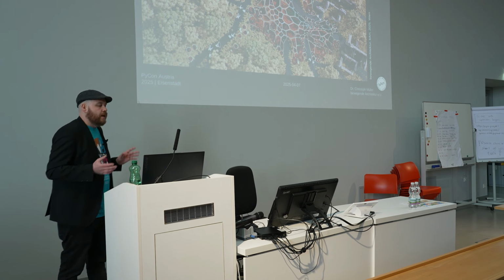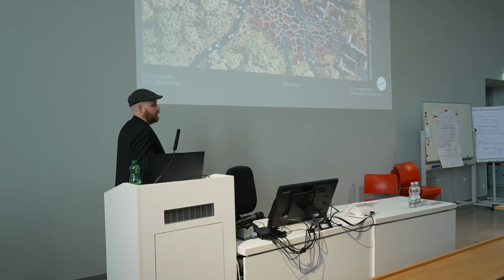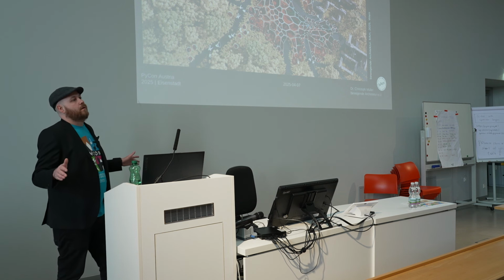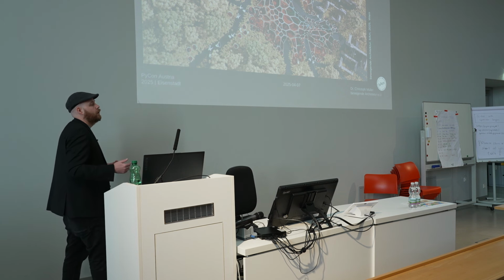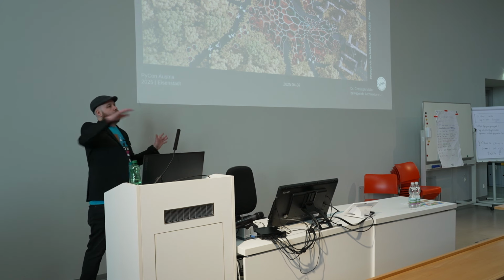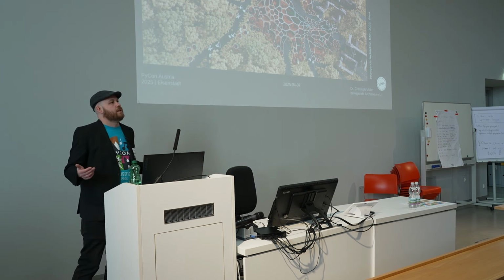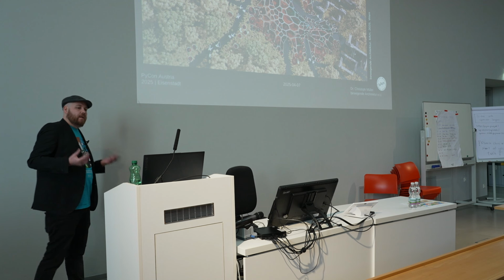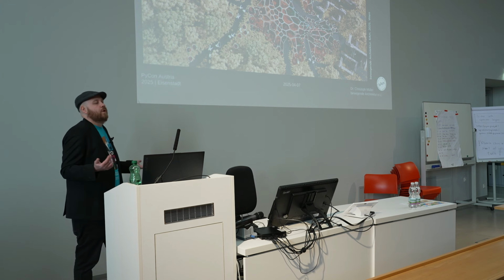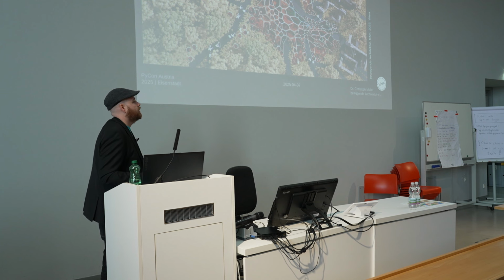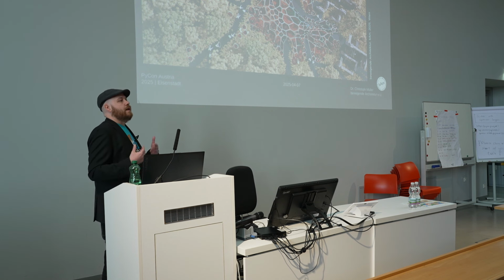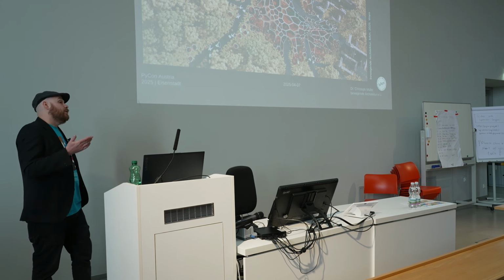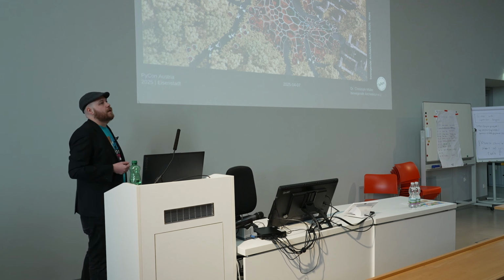But in a membrane structure, there is one very beautiful thing. They are getting more efficient the bigger they are. If you take a look at these Frei Otto structures, there are very large scale structures that are getting more and more efficient the bigger they are. And the statical performance you can compare to a Traglufthalle. I don't know how to call this in English, but it's like a tennis court, where you only have a membrane and you pump it up with air. But to answer your question, there is no structural analysis until now.